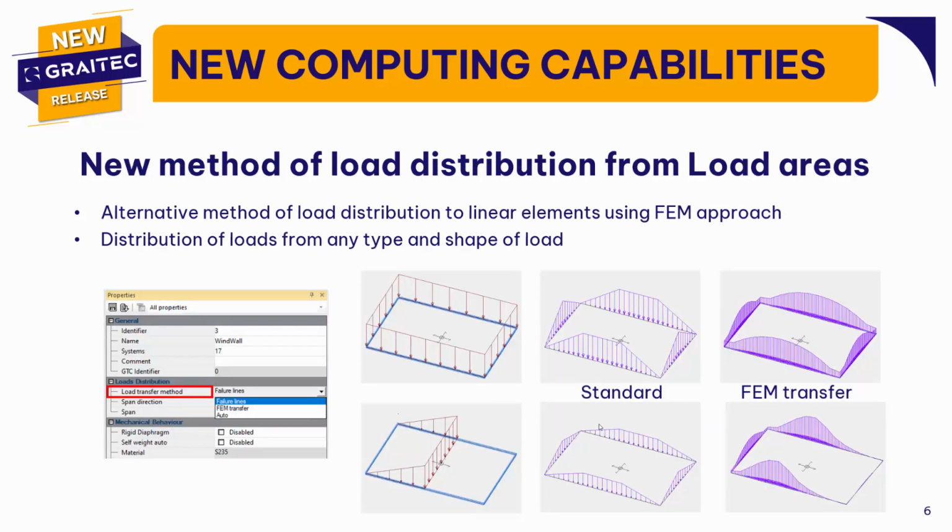So, a new method of load distribution from load areas. As you know, in Advanced Design, we normally use load areas and we apply loads on those. So now we have also added a method. We had the standard method already, and now we have added a second method, which is FEM transfer, which is going to distribute the forces much more accurately for the edge elements.